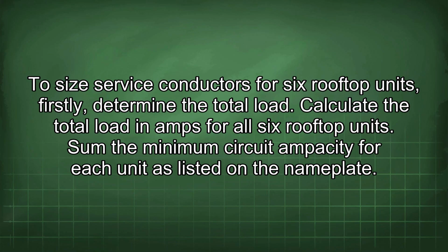To size service conductors for 6 rooftop units, firstly, determine the total load. Calculate the total load in amps for all 6 rooftop units. Sum the minimum circuit ampacity for each unit as listed in the nameplate.